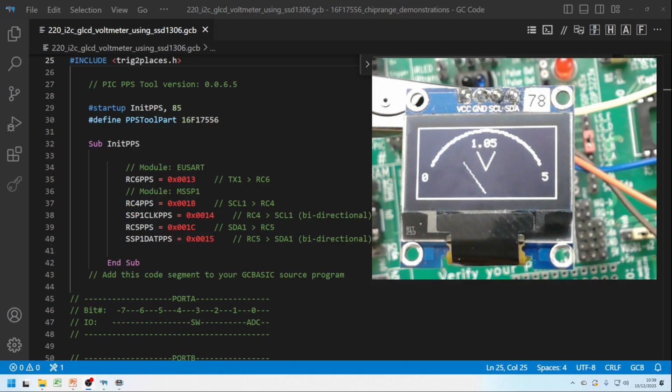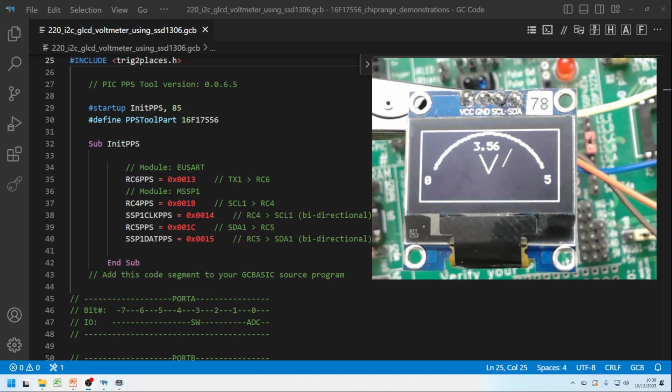All this is over I2C. All this is via the libraries and the low-level libraries that we saw in the diagram. So we're seeing a user program exposed capabilities, GLCD, trigonometry, etc., and then the low-level communication protocol of I2C is abstracted from you. You don't need to do the start, send the data, send. You can if you want to. You can write your own libraries and write your own functions, but these are ways of making it easier.